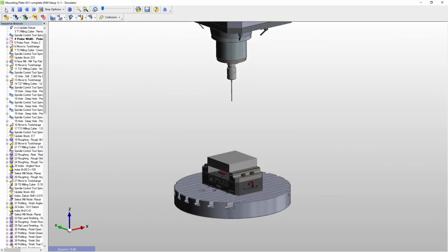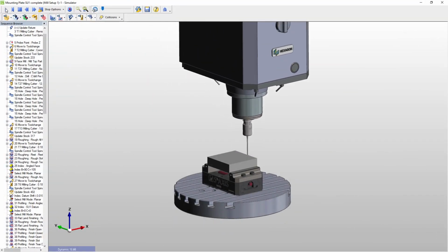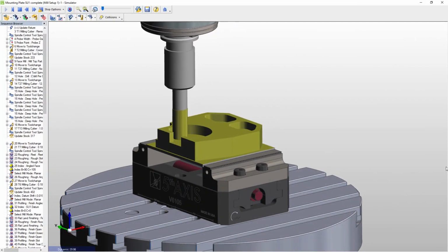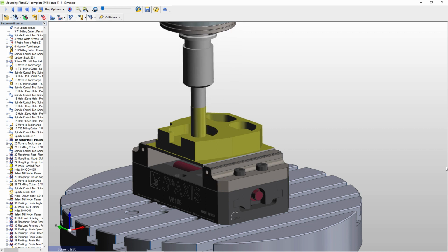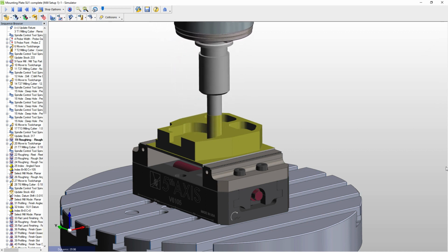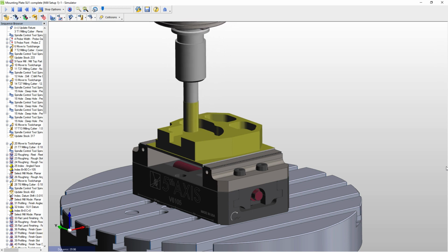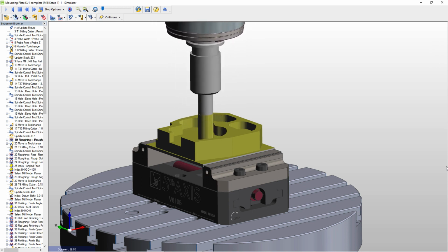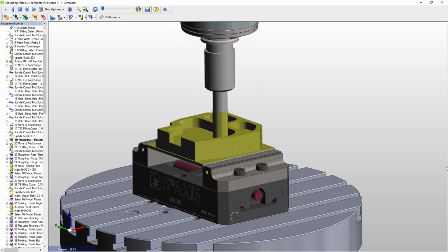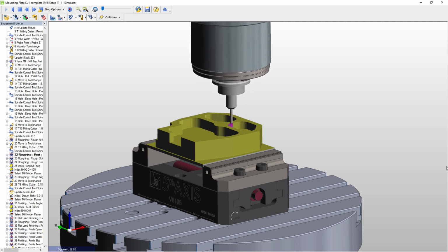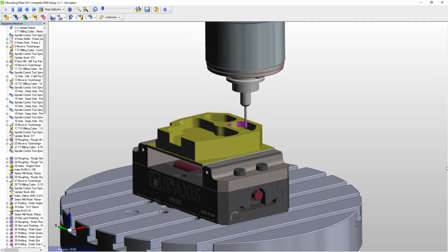The machining process begins with using a touch probe to locate where the stock is and to update the work datum. That's followed by roughing the part all over. The roughing process uses Edgecam's high-speed waveform roughing to efficiently remove material from all accessible areas. The first tool used is a large end mill, and then after that tool's done all the work it can, we switch out to a smaller tool for rest roughing.